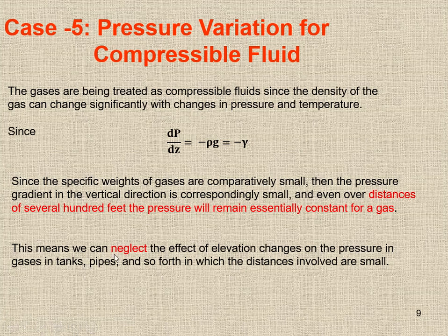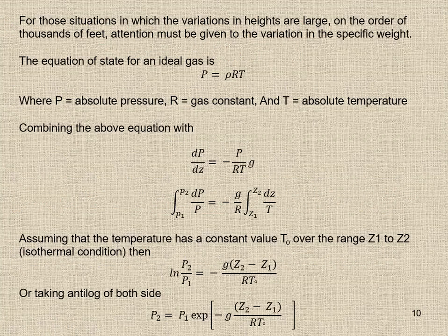This means we can neglect the effect of elevation changes on the pressure in gases, in tanks, pipes, and so forth, in which the distances involved are small. But for situations in which the variation in heights is large, on the order of thousands of feet, attention must be given to the variation in the specific weight.